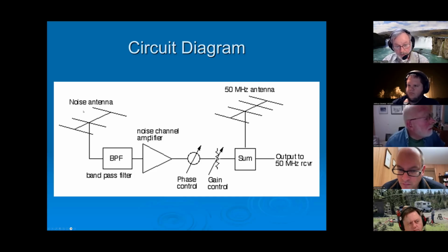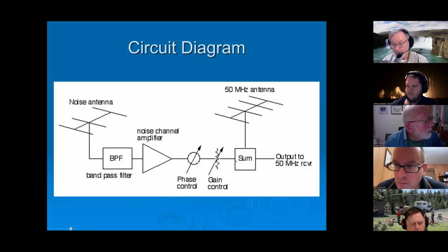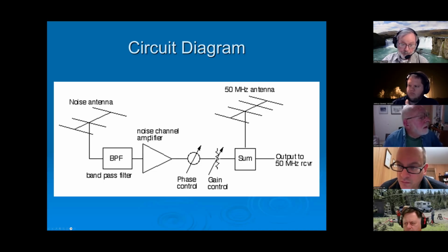So when you get an interfering signal coming in off of the noise antenna, you want that to end up getting into the summing. If this is producing 10 dB worth of noise peak, you want the noise part coming in the opposite direction at minus 10 dB. You want them to be symmetrical. That will properly cancel things out. That signal then gets piped off to your receiver.